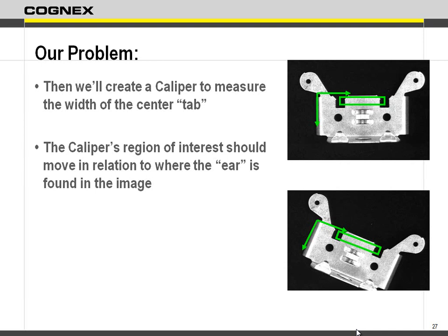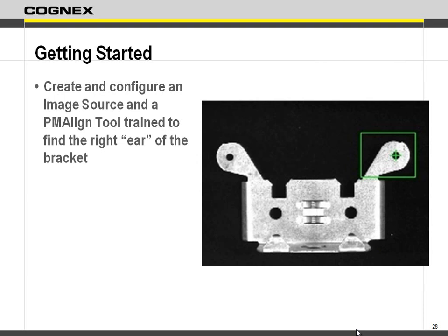Doesn't matter where my part is, but as long as it finds my part, as it rotates, it keeps the regions staying on my part so that they are measuring the exact thing. If I didn't, I would still have my little region sitting up here, and it would be reading nothing. So I want to keep my region small and moving with my part. That's fixturing. So the very first part of a fixture tool is usually using PatMax. The reason we want to use PatMax is because you get both translation and rotation all in one tool. So it just makes things so much easier for us.